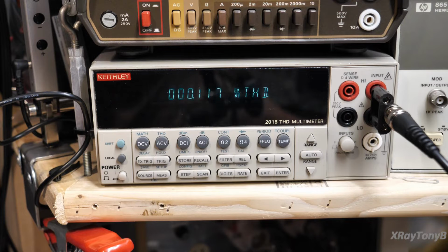And if I overdrive the amplifier a little more, it does go up. Now I'm way into clipping, I would imagine. But I'm right on the edge of clipping right now, and it's still under 0.2. We're right at 0.2, which still isn't what I would expect out of this amp, but not bad. And we can do some final tweaks to the bias and offset to maybe straighten that out even a little bit more. I don't know. We'll look into that too.